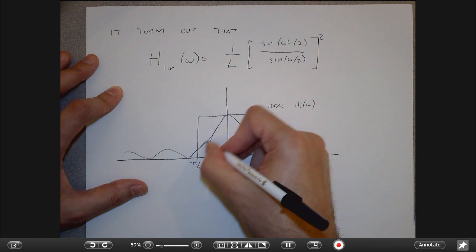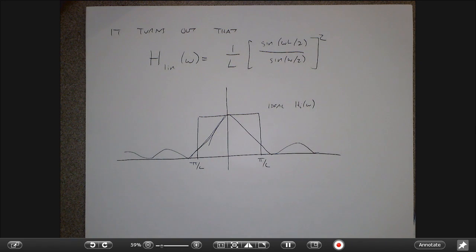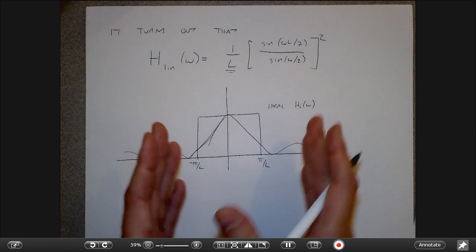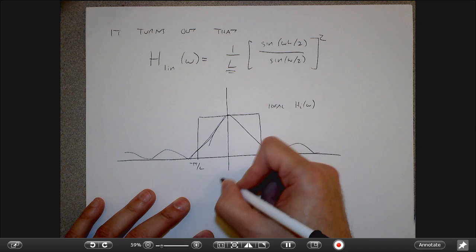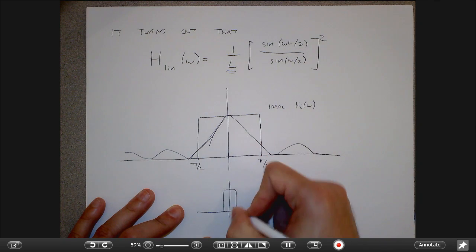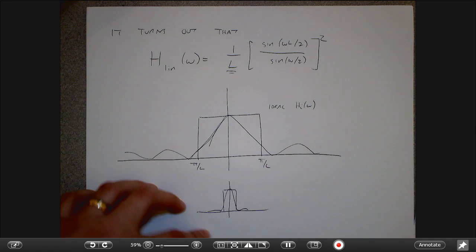And so you can say that the bandwidth of this wavy thing depends on L, basically. And fundamentally, there are ranges in which the ideal reconstruction and the linear interpolation look close enough that you can get away with it, right?